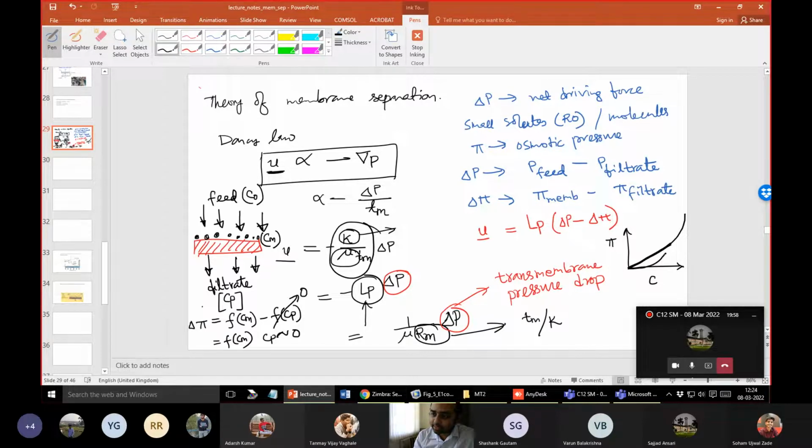So for something like this, the molecular weights of the solutes would be increasing along this direction. I hope I am clear. So as the molecular weight increases, the osmotic pressure reduces. Not only that, this zone of linearity of the osmotic pressure with the concentration also reduces. I mean, the range of concentration over which the osmotic pressure varies linearly with the concentration is also small.